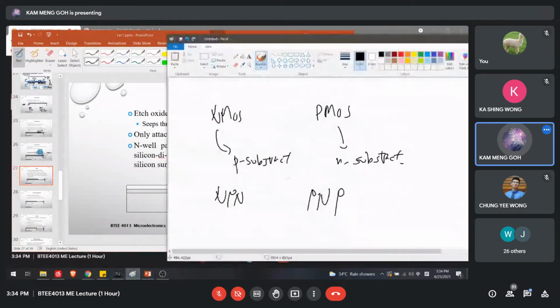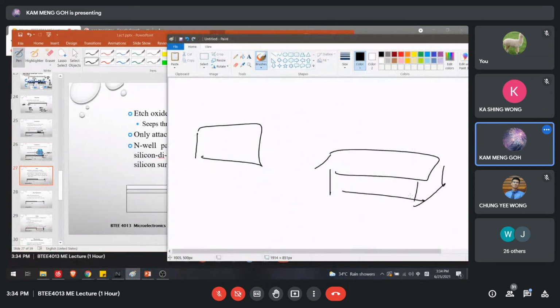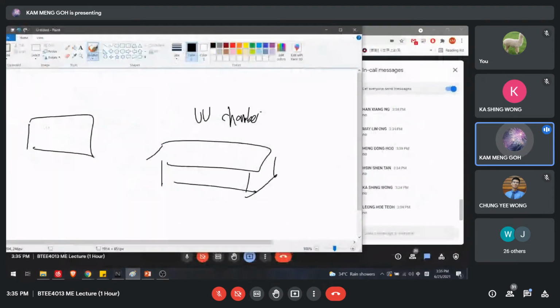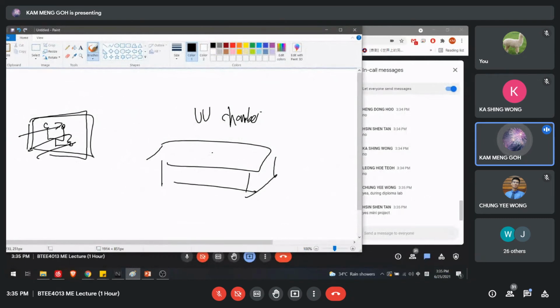So we put the copper board. You remember, we put a copper board into a UV chamber in, let's say, 301. We put a transparent paper on top, right? Then here's a circuit, something like that. We put the transparent paper, then UV light goes through here. So all the region without the cover will be gone, and we just remain with all the region under the black cover. Then we put the board into the etching.